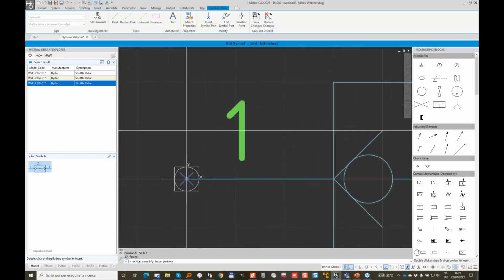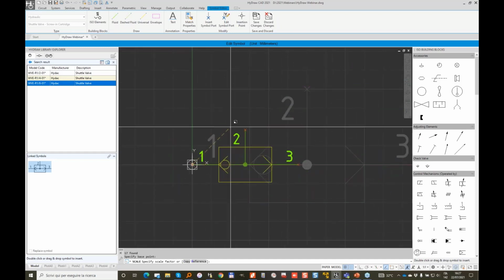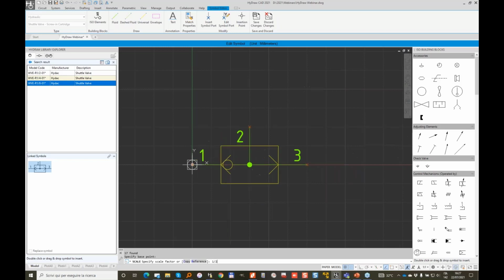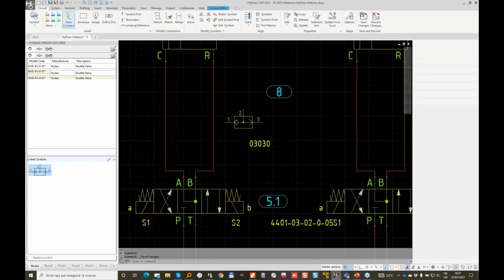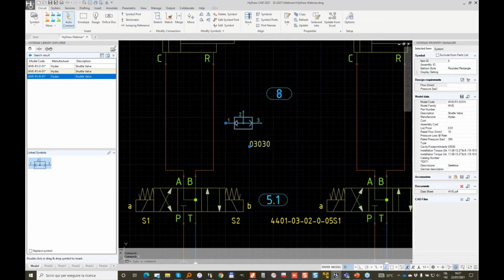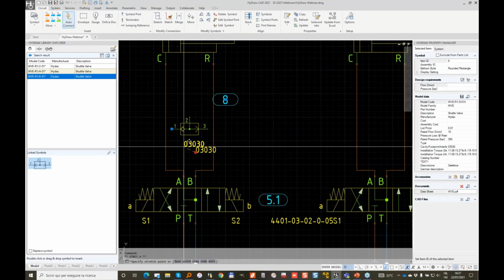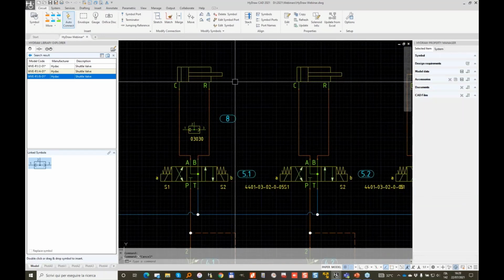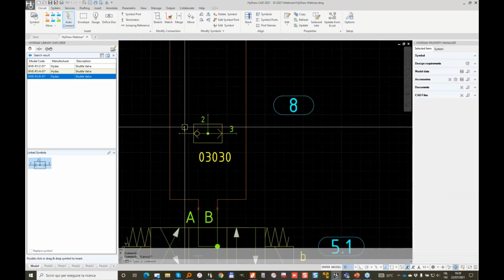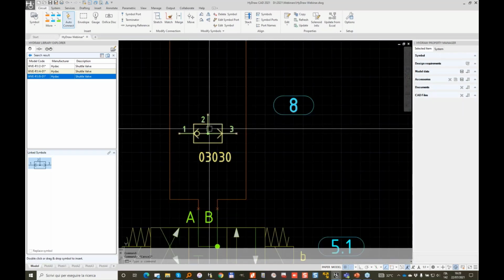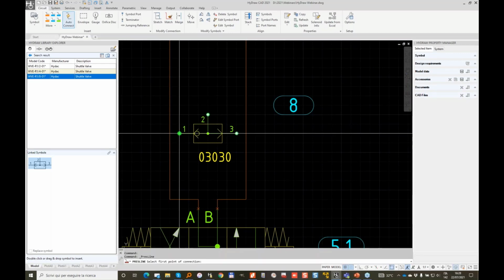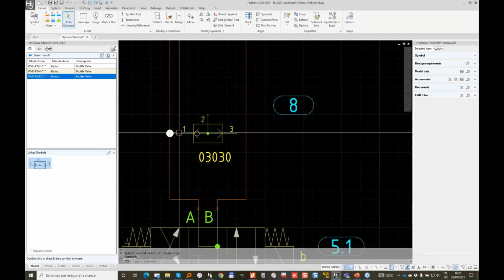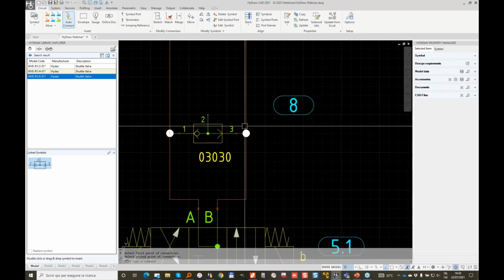Please look at the icon. This is the insertion point. Here, let's make it 0.5, or you can type 1/2. It's scale 1/2. And now we can save changes. And now the symbol will be much smaller. I really don't recommend it, because smaller symbols in a diagram compared to the rest is not really good, and it is also out of ISO 1219 rules. But if you feel it's better for you, you can do it.